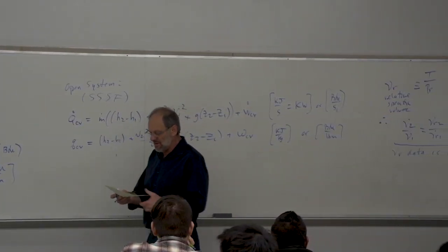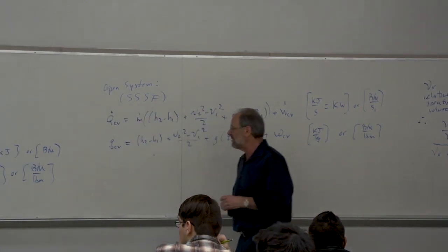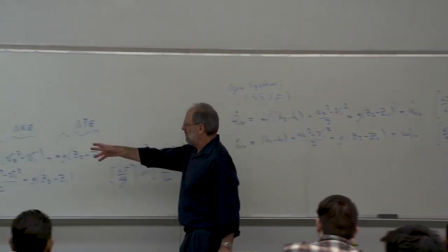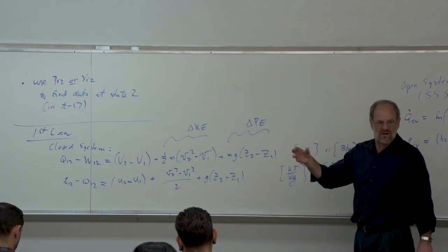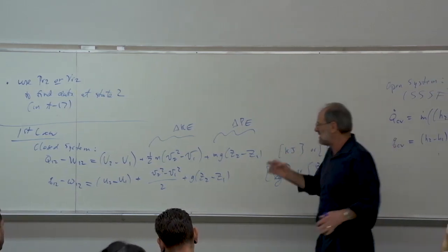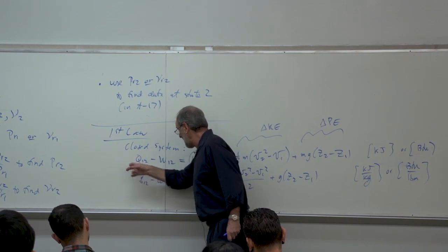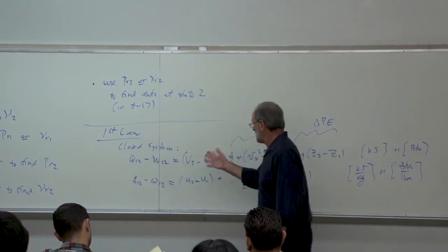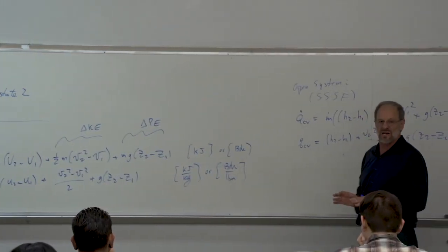Also, we should talk about the sign conventions here. In some textbooks and some instructors, rather than putting Q and W, you have Q in and Q out, and work in and work out. So your equation would say something like Q in minus Q out minus work out minus work in is going to then equal the change in energy terms. I prefer not to do that.